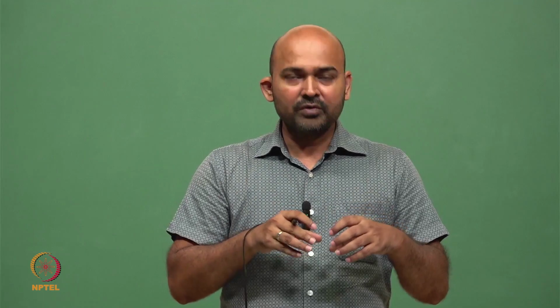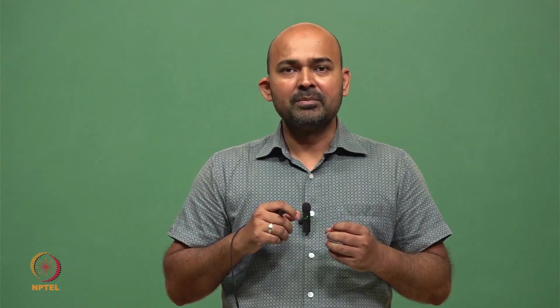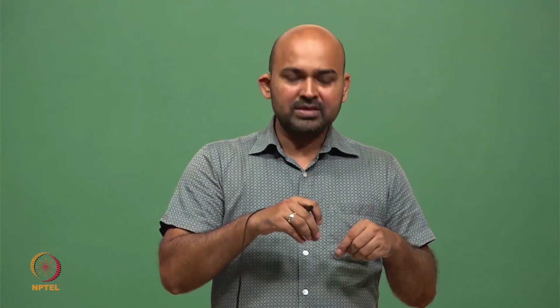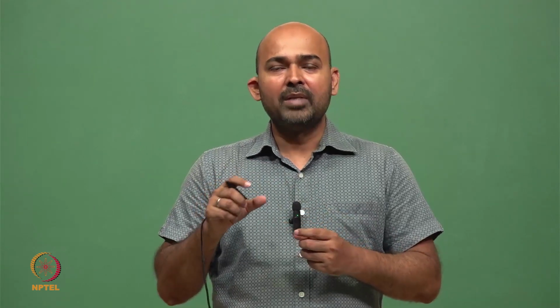Most of the time when we employ a Hall device or a Hall sensor, it is followed by an amplifier, which is a linear amplifier. We can make use of a BJT or MOSFET for making this amplifier, and it is used to boost this signal from the millivolt range to, let's say, volts. So this whole device is now followed by a linear amplifier.